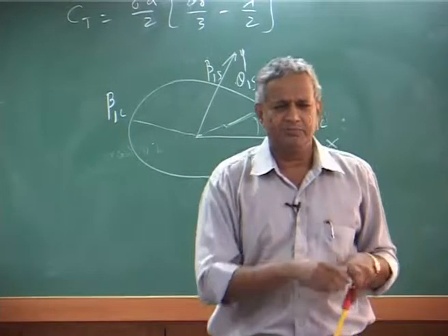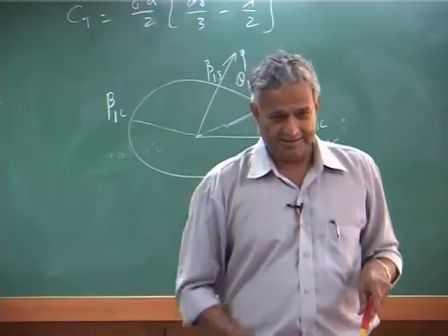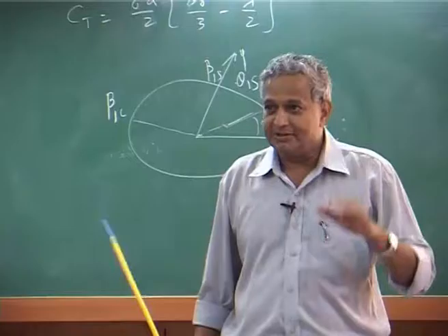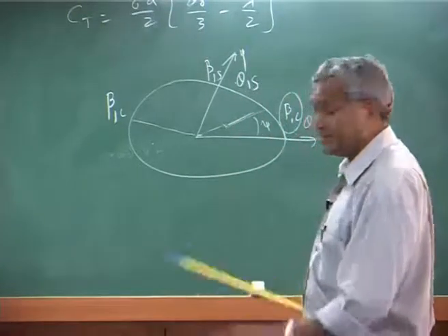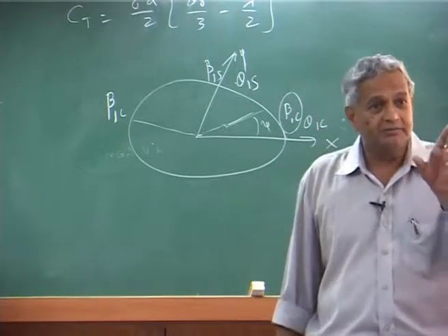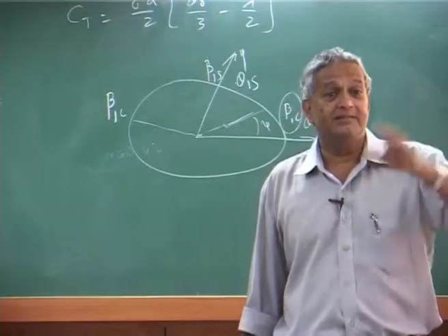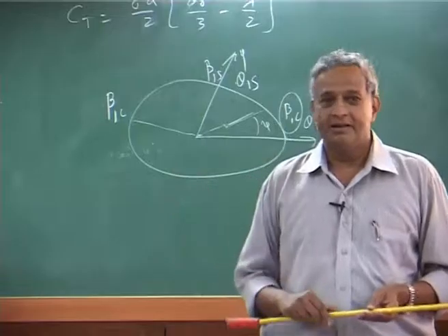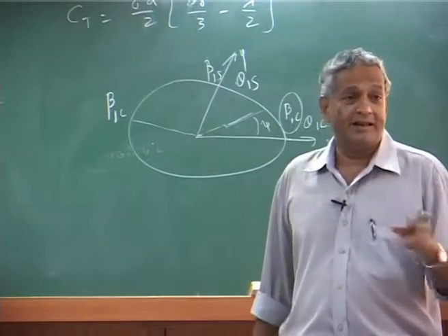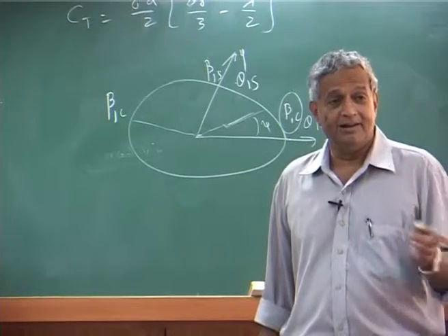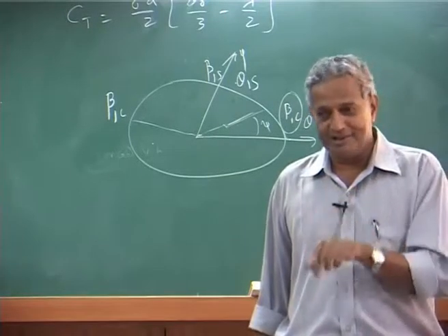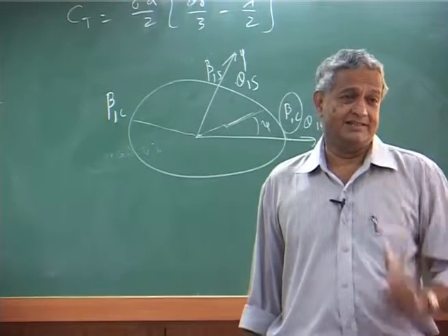The 90 phase shift comes because it is at resonance. If you have studied a little bit more carefully your vibration part, the M x double dot problem, how the phase varies with frequency, all the phase curves, no matter what damping you have, will cross 90 at omega over omega n equal to 1.